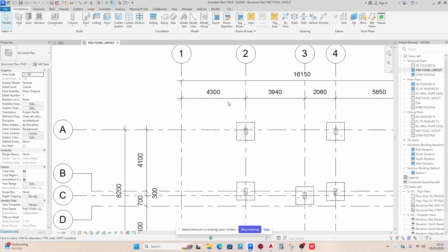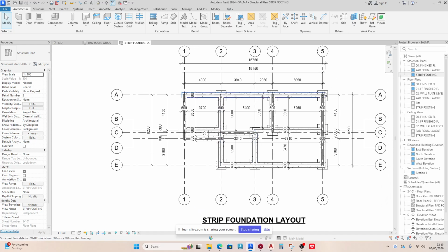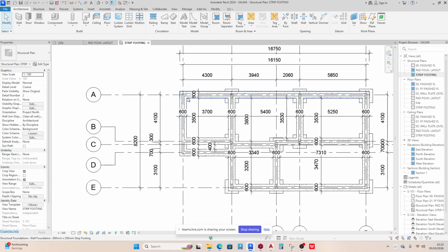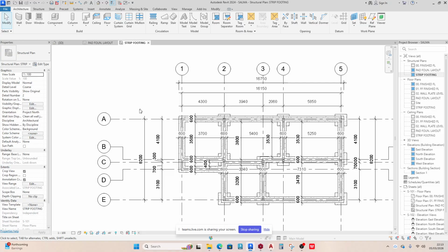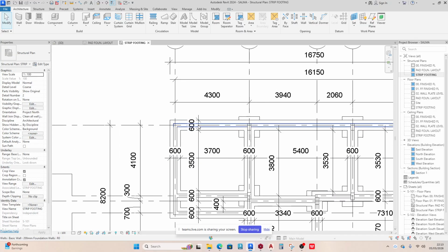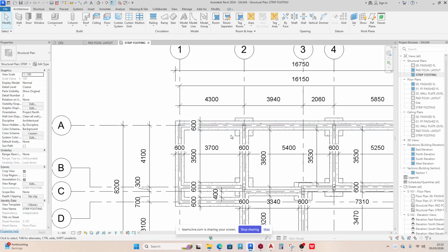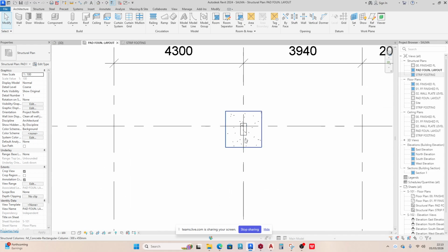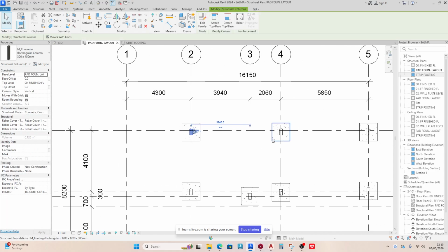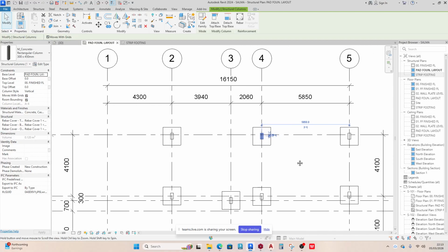Another advantage of always incorporating grid lines, even if there are no structural foundations and it just has walls, is that it would be necessary to have these walls identified by the grid lines. They help in setting out from an architecture standpoint, but from a structural standpoint, most of these structural elements are identified by their axis.